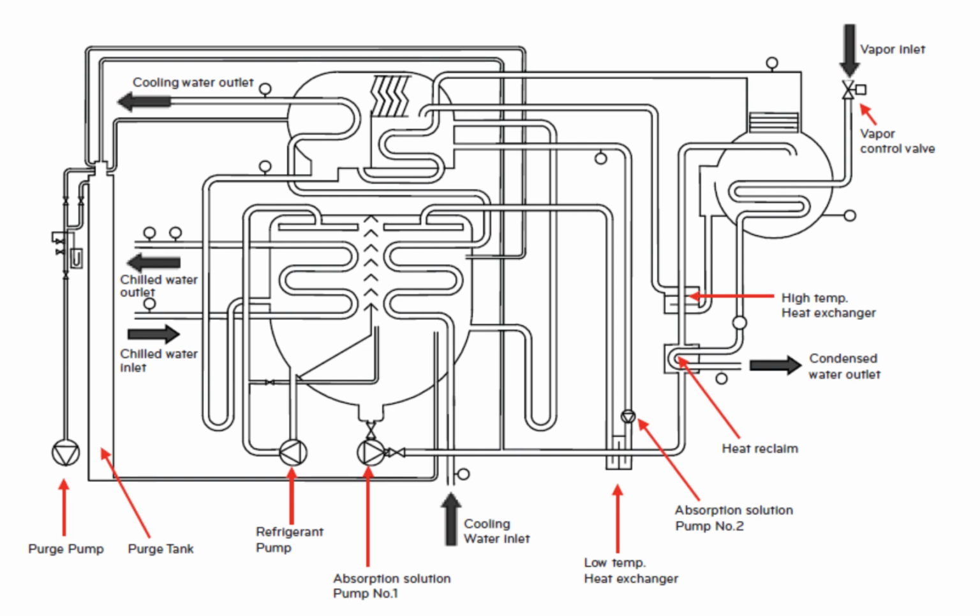Absorption solution, of which the concentration is about 61%, is referred to as intermediate solution. This intermediate solution passes through the high-temperature heat exchanger, lowering the temperature of the intermediate solution to about 94 degrees Celsius, then goes up to a low-temperature regenerator.